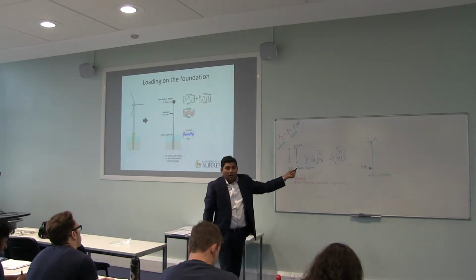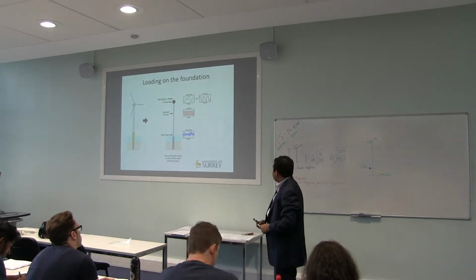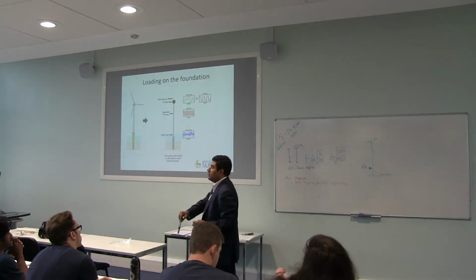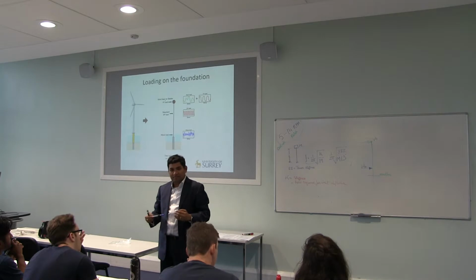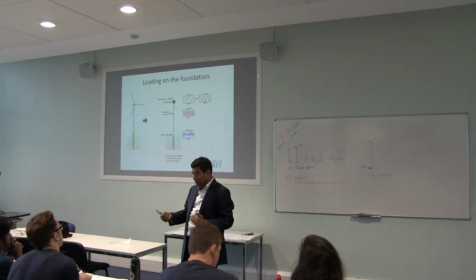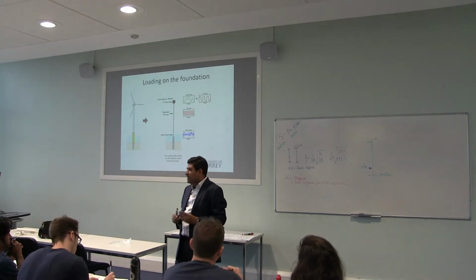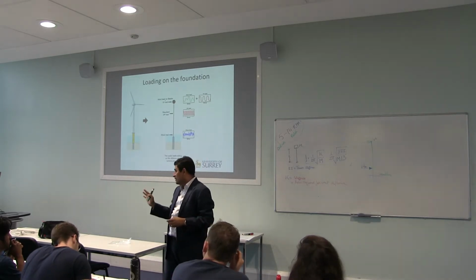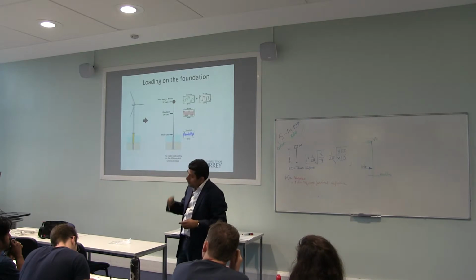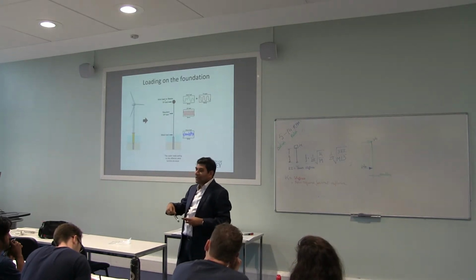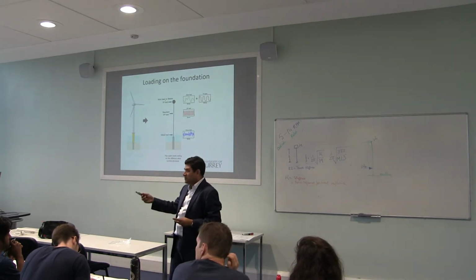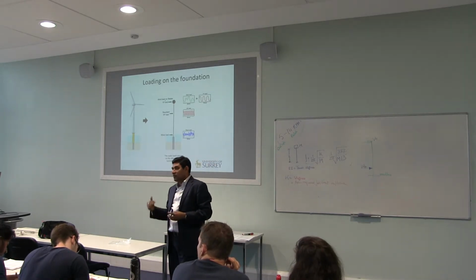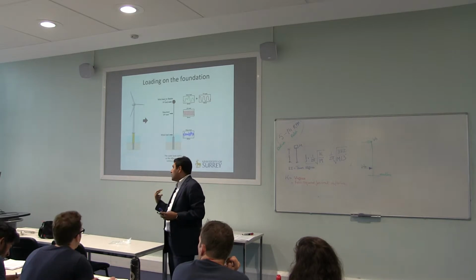What really happens is that there are so many moving parts, and moving parts give you alternating stresses, and that can cause fatigue damage. If the wind is very low, they don't operate it, because you produce power but you do more fatigue damage to your system. Why does the life come to around 30 years?